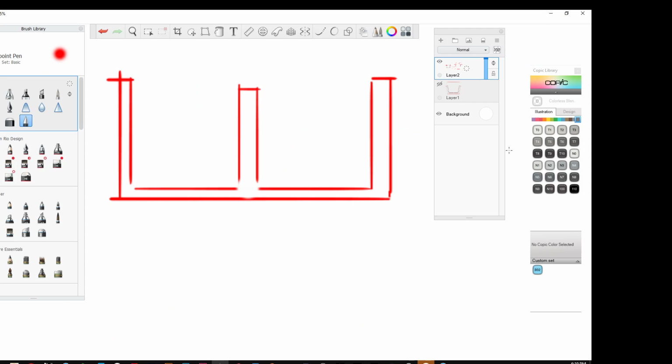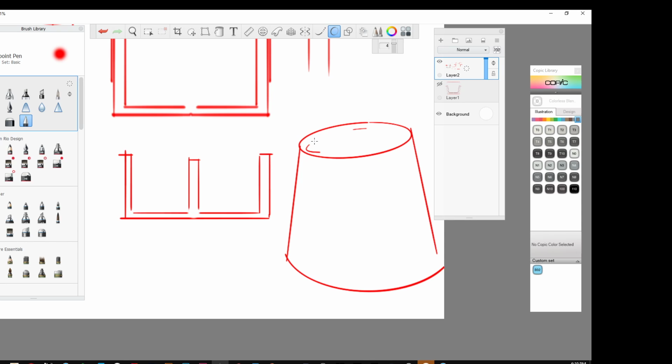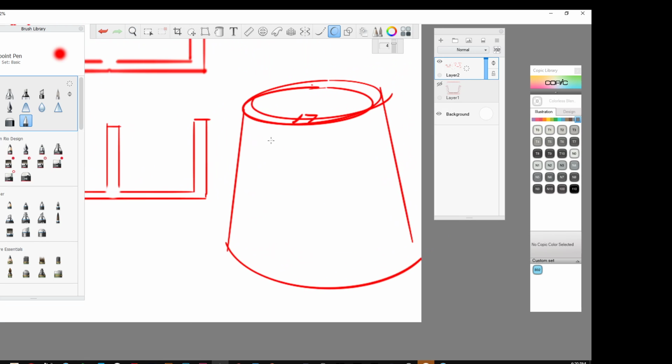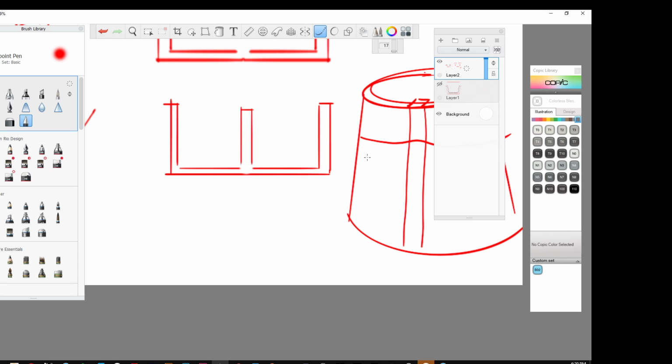But basically, this is what it kind of looks like. Let's say I've got this part, and it's hollow, but in here I've got a rib. What happens is, this surface will kind of come, and you'll see a little bit of a wobble in there the entire way down. Yeah, what that is, is material flow.